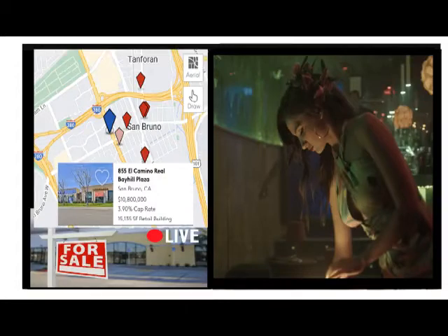Any hardware store customer has probably seen the bulky aluminum foil-clad rolls of fiberglass or rock wool insulation that are sized to fit between wall studs. Such products are easy to install in a home with an exposed ceiling frame accessible through an attic, unless walls are insulated before interior walls are finished. They require the services of a professional. Insulation can be blown into wall cavities, for instance, using the proper equipment. Protective clothing, including mask and gloves, is necessary during any handling of insulation materials.